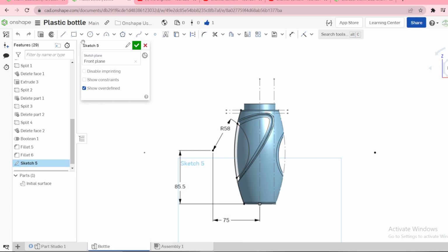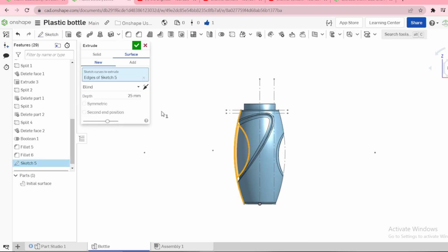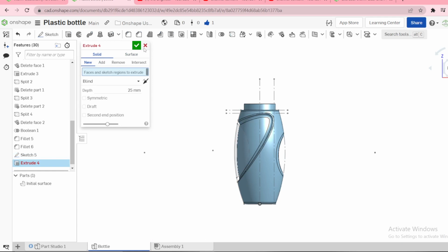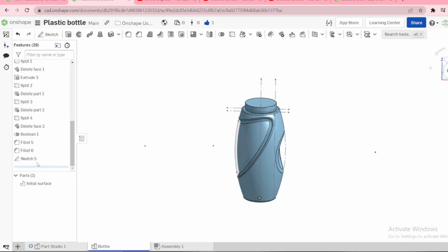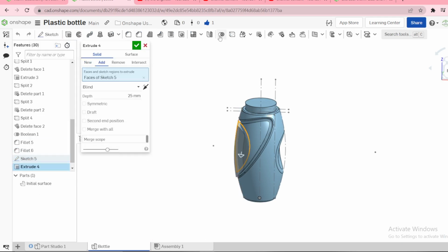Sometimes you don't need to trim. Onshape doesn't care. Okay, Onshape doesn't care. Therefore, remember this one is a part body because we used what we call Boolean. And whenever you have a closed surface body, when you use a Boolean, it becomes a solid body.